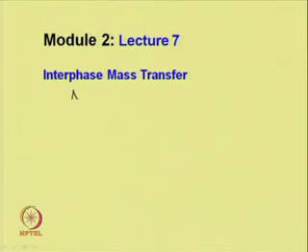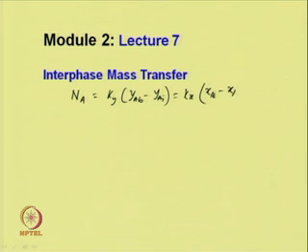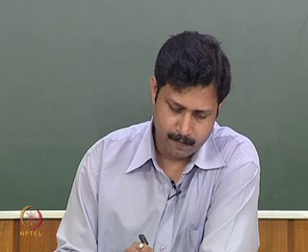So, we cannot calculate the flux using, say, k y into y A B minus y A I, the interfacial concentration, or k x into x A I minus x A B. We have seen that we can use the overall mass transfer coefficient concept to calculate the flux.